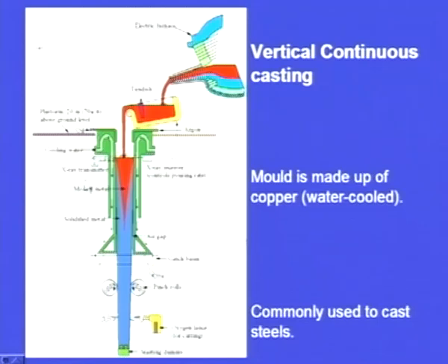So, here we can see one X-ray transmitter and here we can see X-ray receiver. Here is the tundish, means a special pouring cup or the special pouring basin, and we are pouring molten metal into this tundish. The molten metal from this tundish is flowing into the mold.